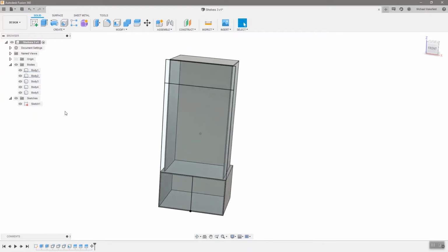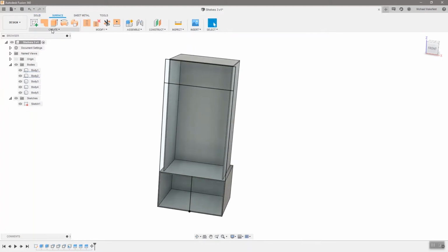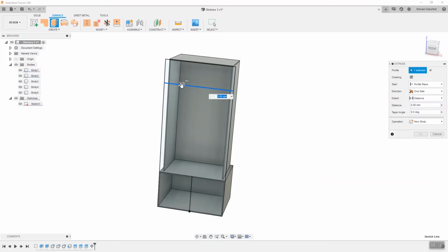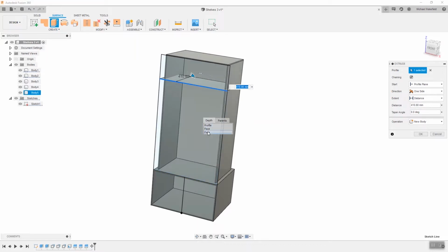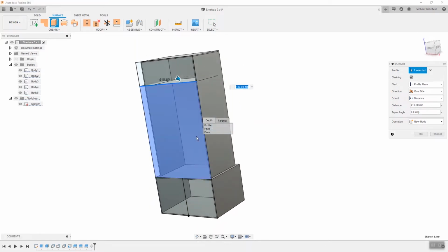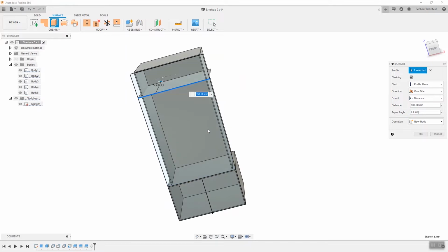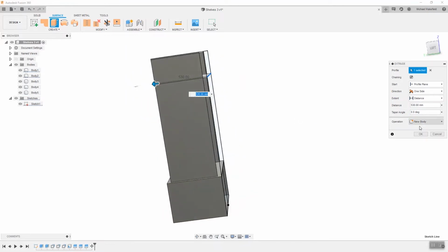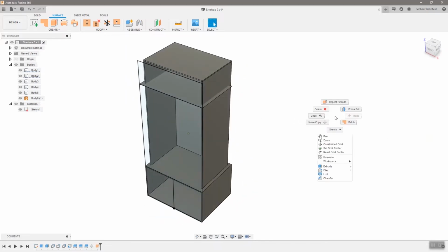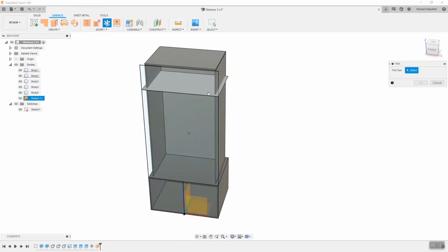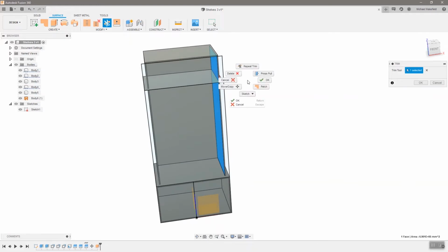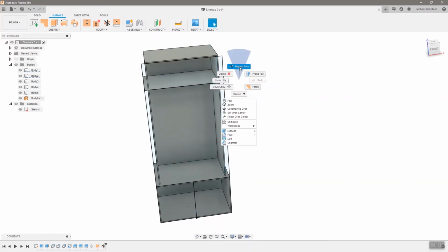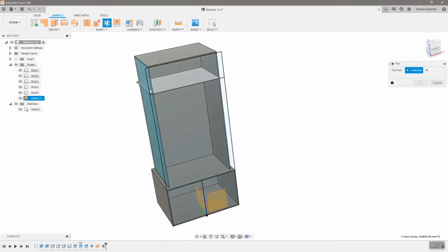The next thing I decided to do was turn that sketch back on and then use the surface commands here to describe that upper shelf. I'm going to push that all the way back to that back panel, and that's one of the reasons I pushed the back panel in first before actually creating this shelf. This surface is too large. It hangs off over the edges, but I can use the command trim surface to select again those inner edges, those inner faces, to trim that surface.